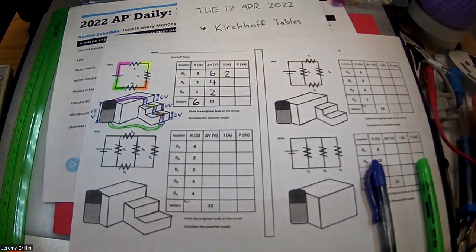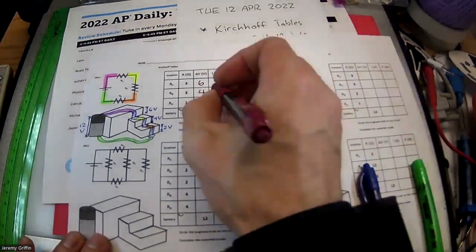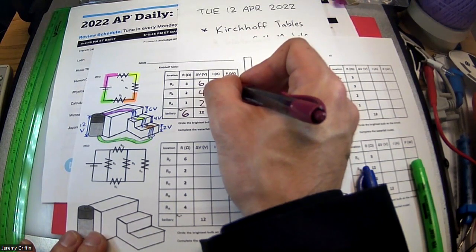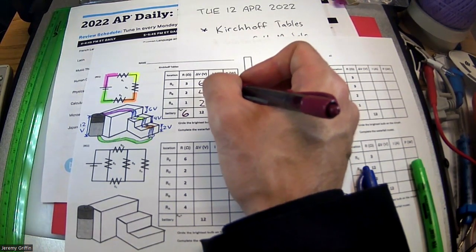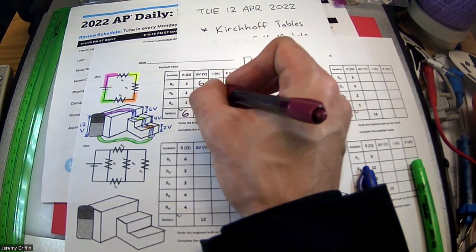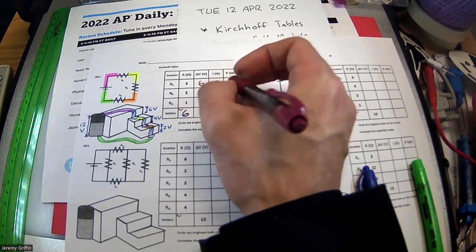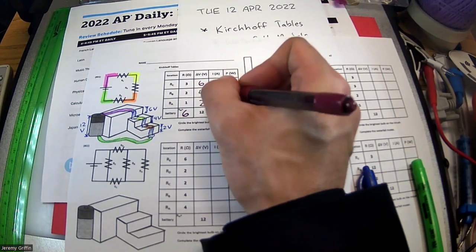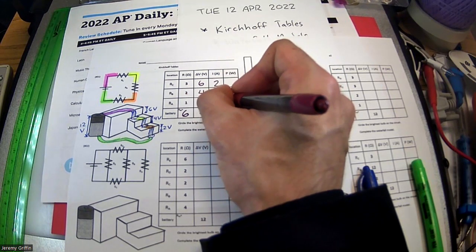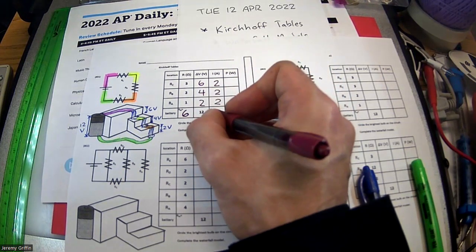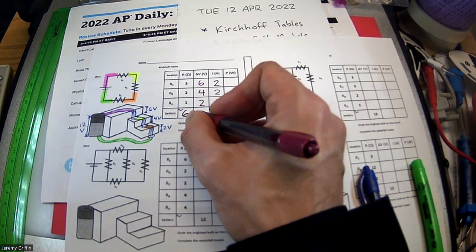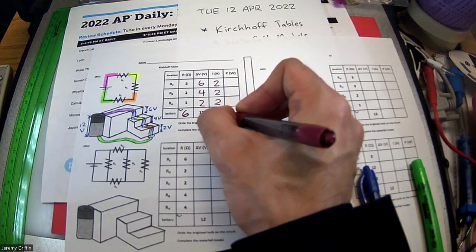Now you might very quickly pick up a pattern here, because all I did was take this many volts divided by this many ohms, and I got the current going through that part of the circuit. Couldn't I just copy paste that procedure all the way down? Ohm's law for the next row: 4 volts on 2 ohms. That's also 2 amps. And for resistor A, 2 volts acting on 1 ohm, that's also 2 amps. How about across the battery? 12-volt battery, 6 ohms equivalent resistance, 12 over 6 is also 2.